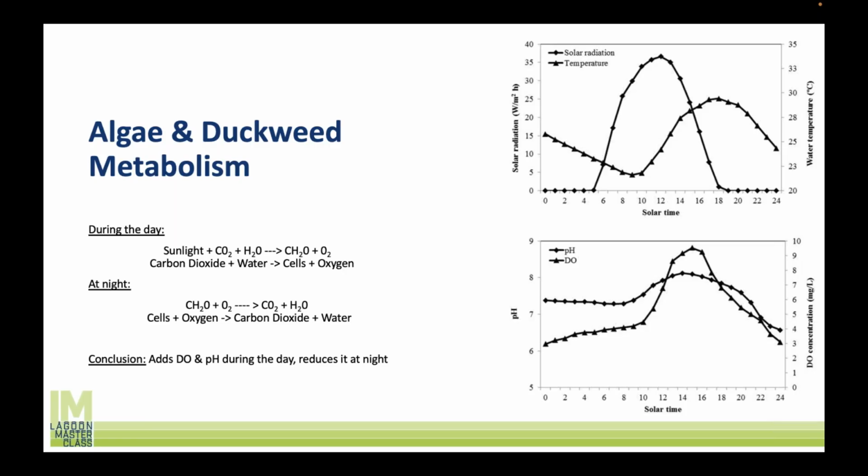And we also find that algae kind of move around in the water column across the cycle, right? They sink at night and they rise up to the surface during the day. So they're sinking, rising, sinking, rising. And this is one of the reasons why simply putting your effluent pipe, let's say 36 inches underneath the water, doesn't necessarily work to avoid pulling algae out of your lagoon. Because of that sinking and rising effect that algae have over their 24-hour cycle.